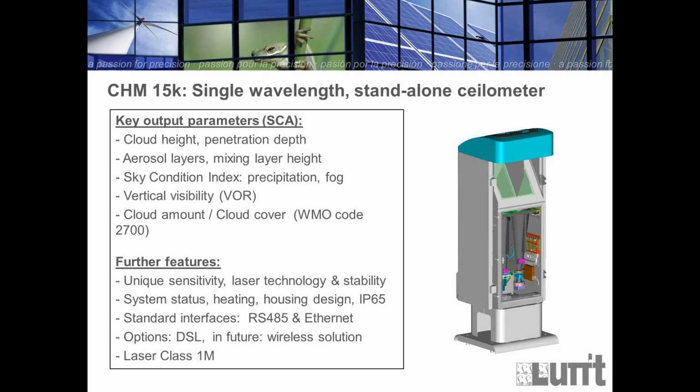There are many other hardware-driven topics, for example the sensitivity of the instrument, the laser technology which is integrated, and also the interfaces. So we have these two interfaces: the serial interface, RS-485 duplex mode, and the Ethernet option to directly connect the instrument to LAN, so you can work with the web interface on the instrument and get the data directly.